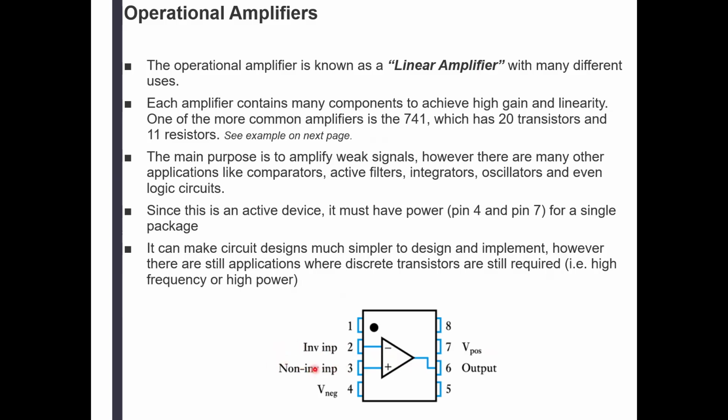And this is an active device because it needs to have power applied to it. So here, don't forget to apply positive power to pin 7. We're going to apply the negative power, and some of us already have accomplished that: plus 15 volts and minus 15 volts, connecting two outputs of that power supply. That's why we're practicing that. We're going to do some more of that this week during the lab, just so everybody's comfortable with doing that, so we're not wasting time trying to learn how to establish the power supply.